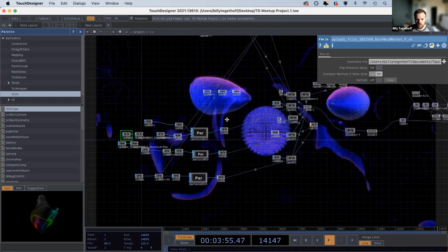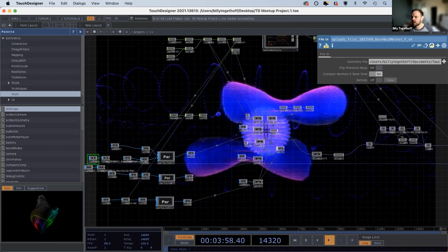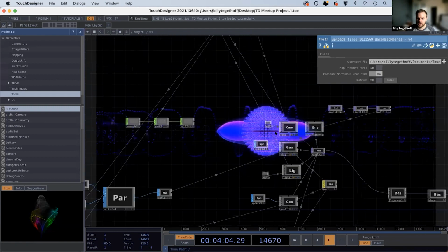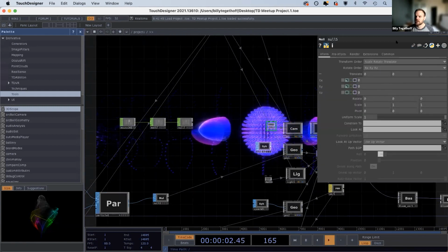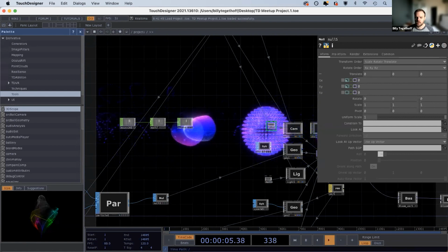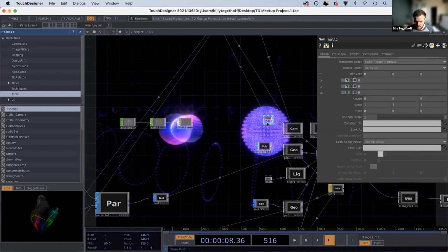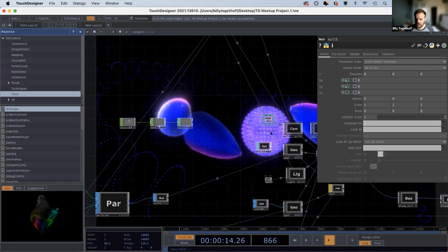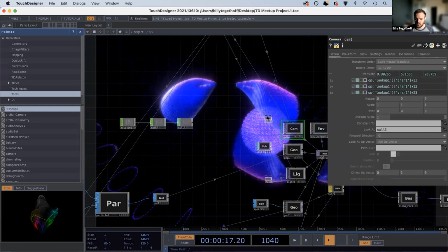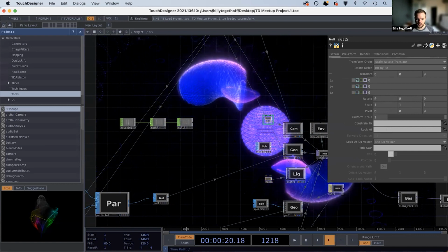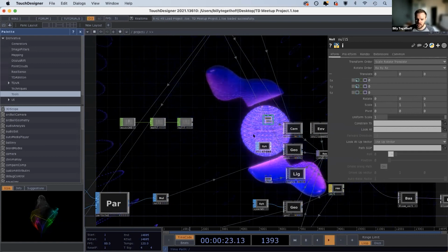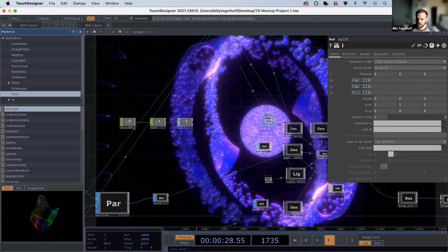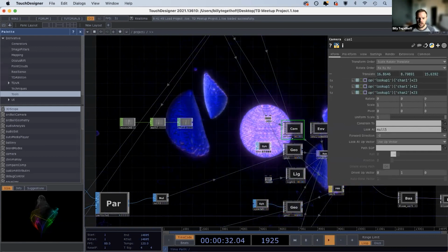Before we get into the project here, let me just note the time so I don't go over. I do want to talk about one thing that I discovered recently that I thought was handy, so I just want to share it here. I didn't know why using a null comp as a look at in a render network actually worked. I just had seen it in tutorials and thought, okay, well, I guess if I want my camera to be focused on a central point, I need to have a null comp as my look at in my camera here.